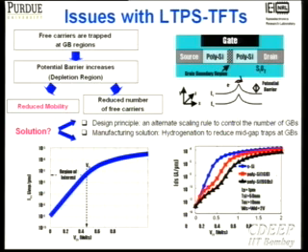To that effect, we optimized these devices under certain constraints: the process technology constraint and the temperature constraint. For that, the design principle that we used is an alternate scaling rule. What do we mean by an alternate scaling rule in this case? I'm not going to be able to have a good oxide. Even if I'm not scaling my oxide thickness, can I get a reasonable transistor out of it? It turns out it's possible by reducing the body thickness of the device, so my scaling is going to be a little bit different.